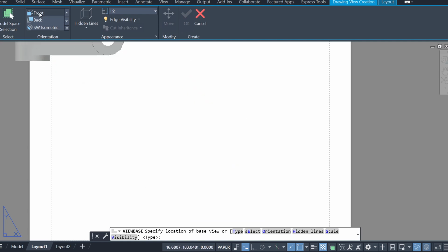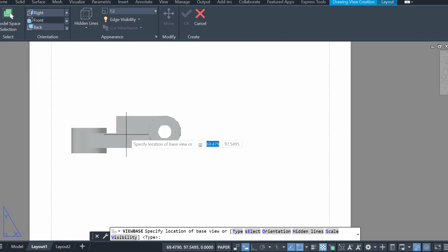Usually, we want to click the front view as our parent. So, dito sa orientation, pili tayo ng front. So there's a bunch of options, no? May southwest as isometric, southeast, northeast, northwest, etc. Kailangan natin is yung front if we want to follow the sort of ES1 standard, no? So front yung pipiliin natin.